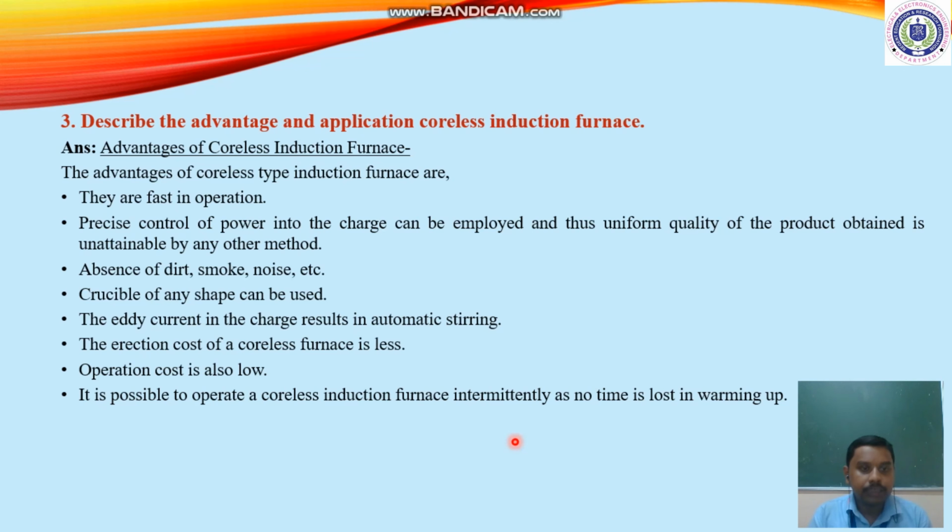There is an absence of dirt, smoke and noise, and a crucible of any shape can be used. Next, the eddy currents in the charge result in automatic stirring. The erection cost of the coreless furnace is less, and the operation cost is very low.